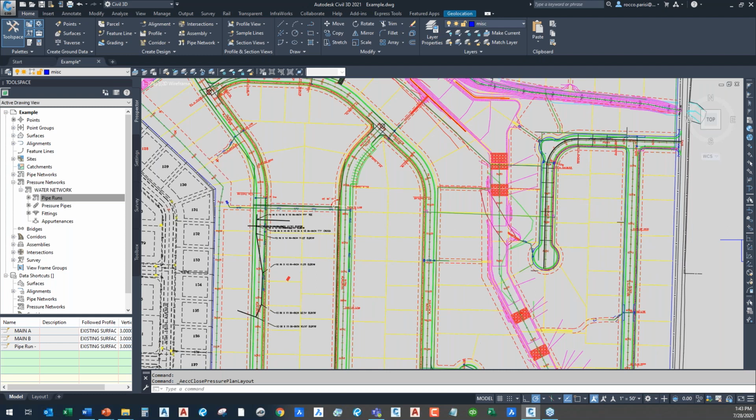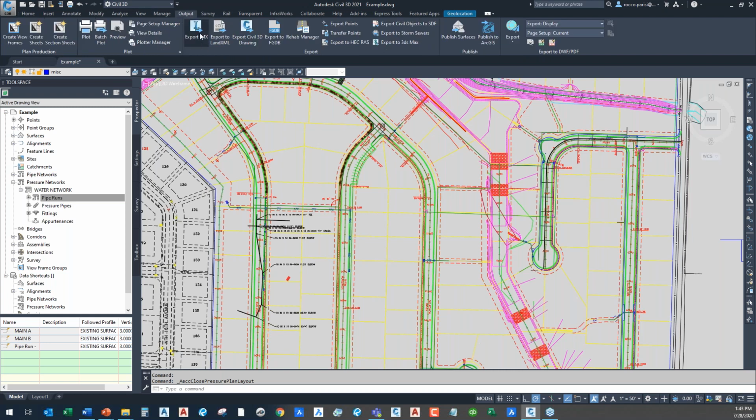And again, most of that work and most of the processing happens in Infraworks, which isn't really what we're talking about here today. But just to kind of at least show you guys, right, that you can go in and you can just go to the Output tab and you can just export any Civil 3D data, right, particularly your road corridors, that will go out and you'll save it as an IMX file that can then be imported into Infraworks, right, and then transferred over.